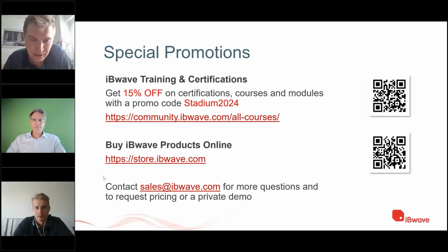I would reply this way. We have used measurements for comparison, and we have adjusted the propagation model for one of the stadiums. After adjustment, we performed iterative new modeling, and exactly this project was about 4G to 5G upgrades. This design we expect to be deployed. So I cannot say right now that it is deployed and we see the result. However, if you ask me, I would not go and deploy without verification with a prediction instrument, of course.